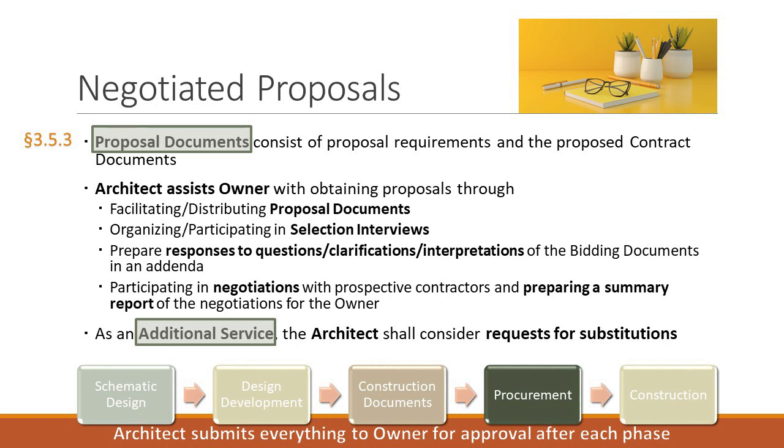Now, if the proposal documents permit substitutions, upon the owner's written authorization, the architect shall, as an additional service, consider requests for substitutions, and shall prepare and distribute addenda identifying approved substitutions to all prospective contractors.